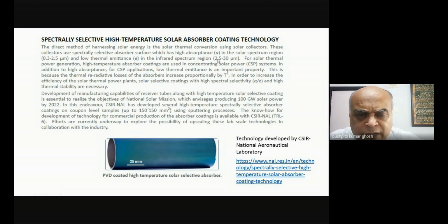And so you want a coating which will exhibit like 100% absorptance. All of it will be absorbed. You don't want it to reflect the radiation, because reflection means I'll lose it. So I can't, for example, take an aluminium foil reflector. It will get reflected and bounce back. So I need something which will only absorb and not reflect the radiation, nor transmit the radiation. It will absorb, and I want it to be as high as possible.